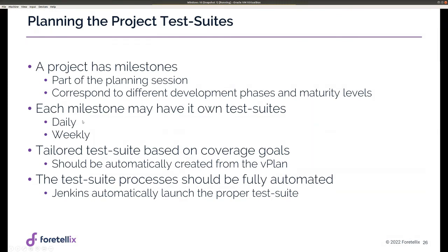Now, each milestone may have its own test suite that needs to be executed. It could be daily or weekly. And on top of that, like we said, there are tailored test suites based on coverage goals that you might want to achieve. So you might want to say, well, this use case of a junction, I want to try just that because maybe that's a modification that I did. Or I want to try things in fog, so just create a test suite with all the scenarios where fog is involved. You can do that in a click of a button.